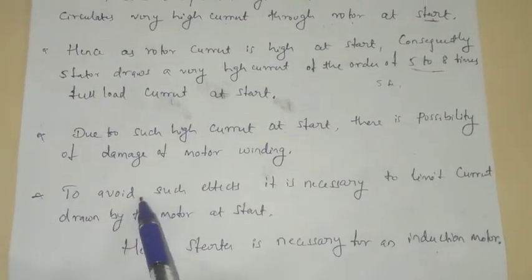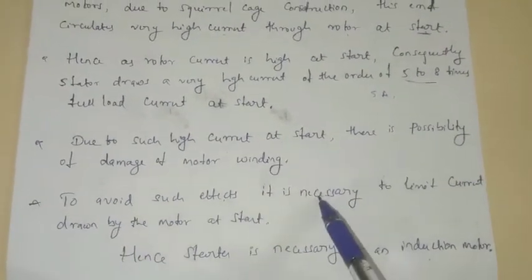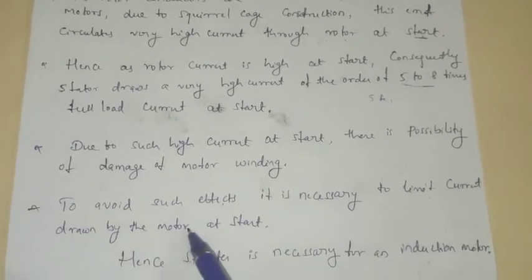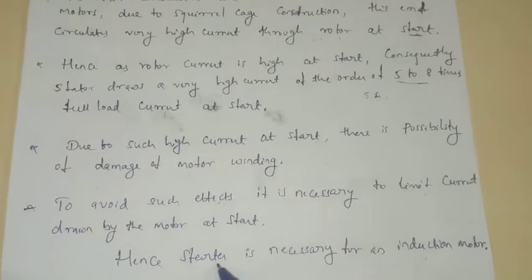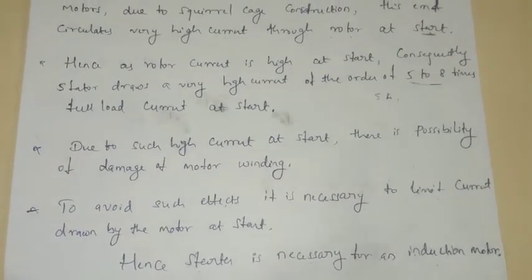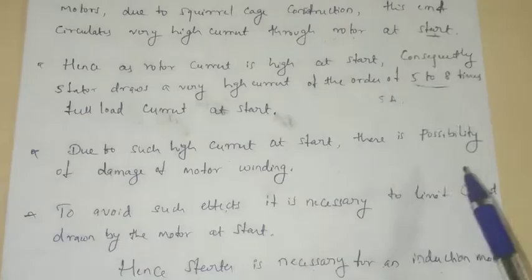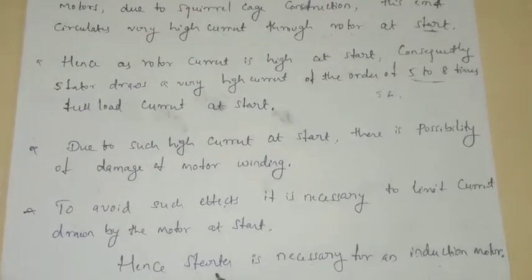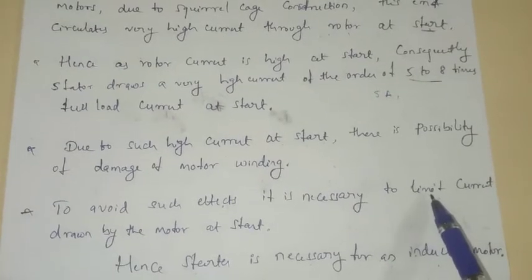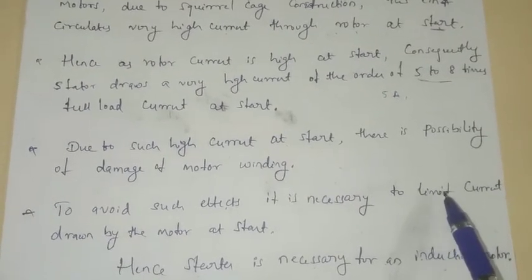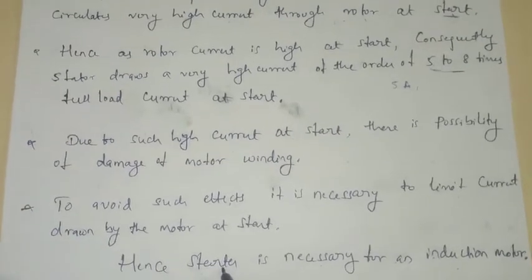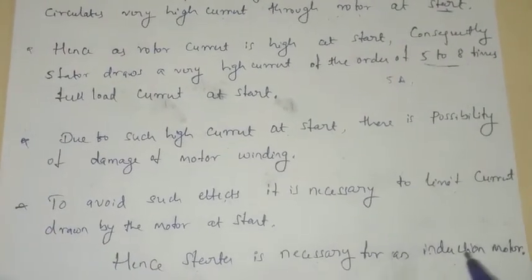To avoid such effects, it is very necessary to limit the starting current drawn by the motor. Hence, the starter is very necessary for the induction motor. In a simple way, starters are necessary to limit the starting current, because at starting condition the current is very high. So we need to limit the current to a minimum. For that purpose, the starter is necessary for the induction motor.